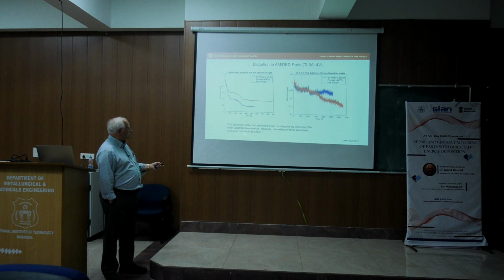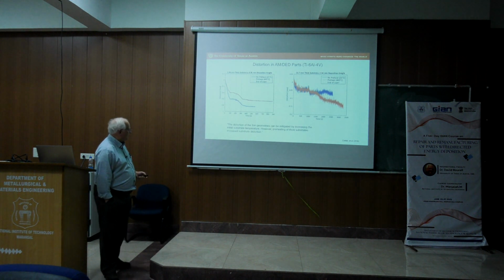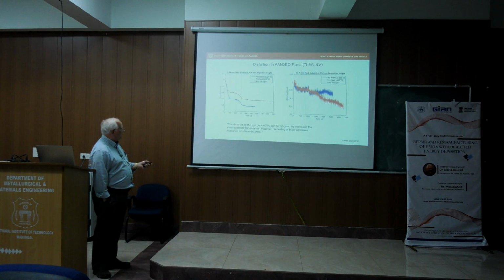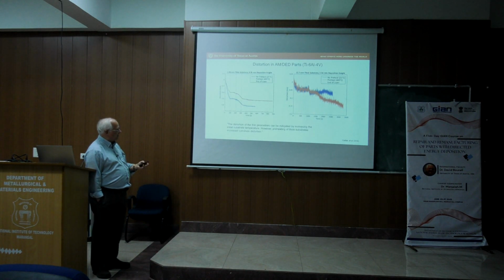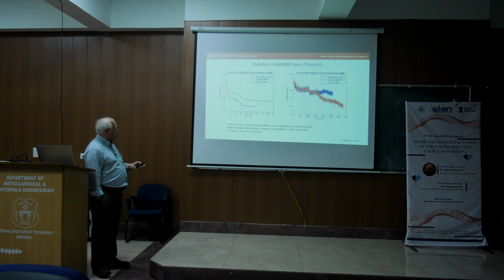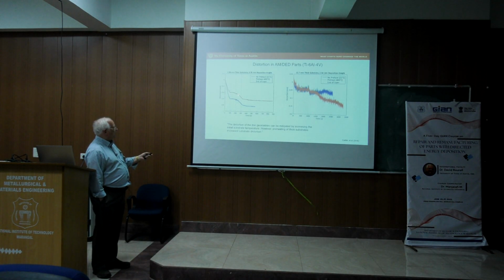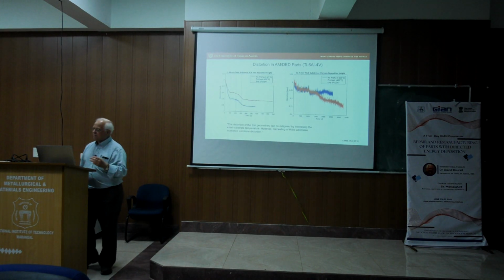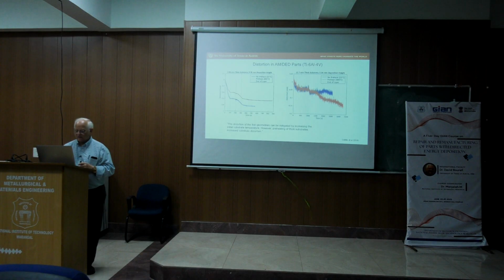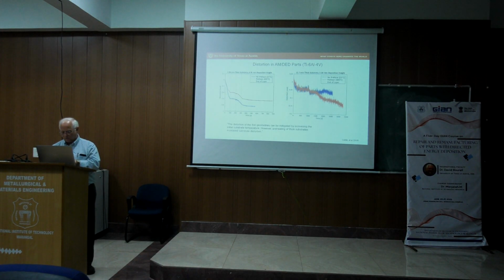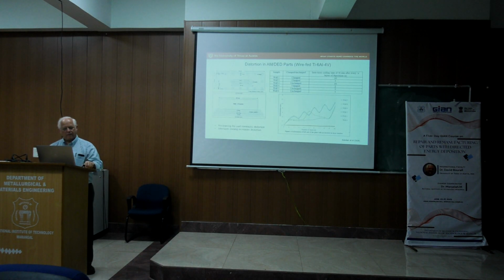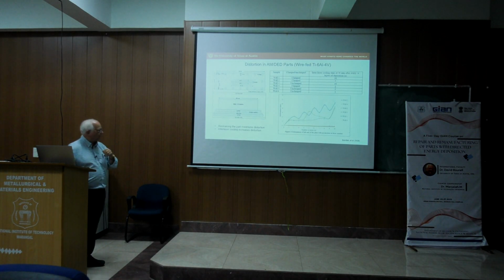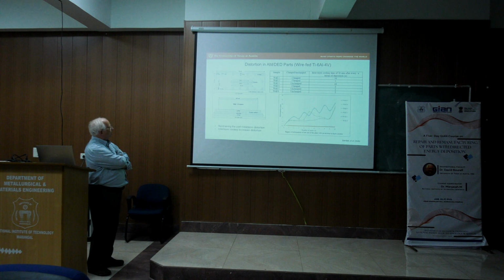where for really thick parts we have an increase in distortion. You can see this from the quote I got from the paper: distortion of thin geometries can be mitigated by increasing the initial substrate temperature. That's shown here. However, preheating of thick substrates can increase the substrate distortion. So we have to be careful about how that works. This is some other work that shows the effect.